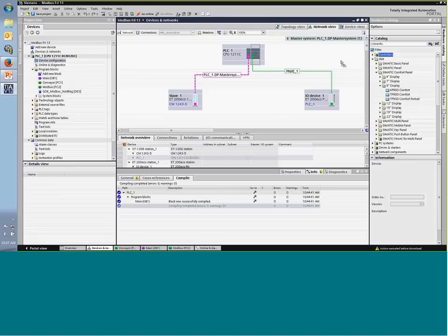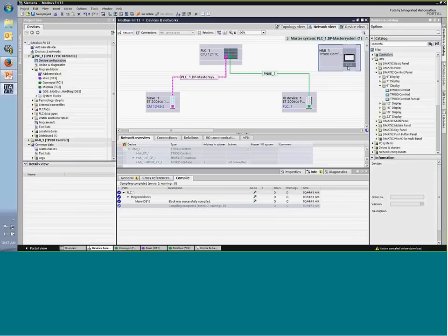So the HMI is networked to the project, and you can see another green box right here. So I can go ahead and connect that to that. So now it's brought a comfort panel inside our project along with our CPU and the existing remote I/O, and we will need a switch here because we don't have the 1215, and we just brought a comfort panel in and we can program our comfort panel.